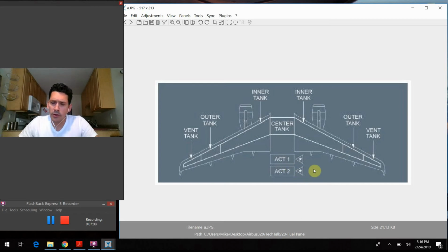One other interesting thing to point out to you guys, we might have mentioned it in a prior discussion: anytime in the Airbus manuals you see this little triangle with an asterisk in it, it just means it's an option, that not all the airplanes are outfitted with this. It's just for the purposes of when they publish the manuals, so it's a little bit less printing. You'll see these a lot of times, and you just need to be aware that it's there. It doesn't affect a whole lot, because obviously we know the configuration of the airplane we're operating. But it took me a little while to figure out. I had to go digging for it, but that's what these mean.